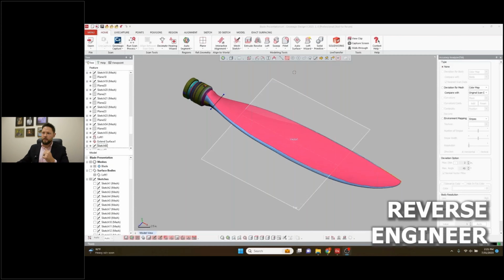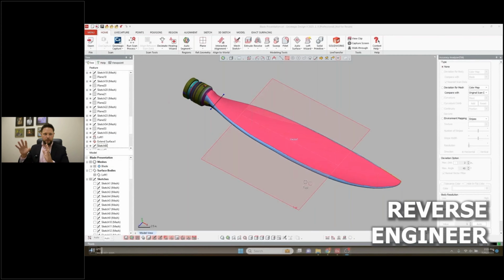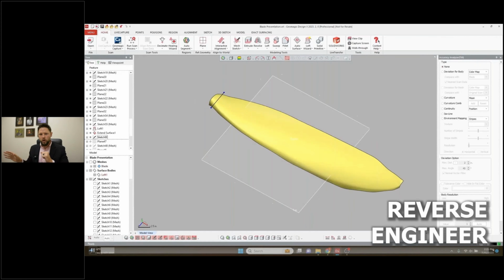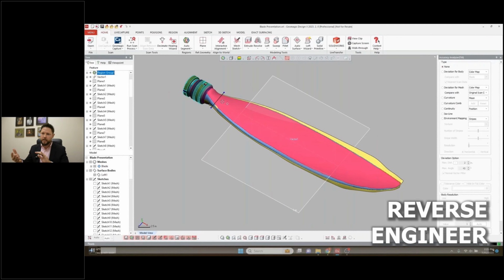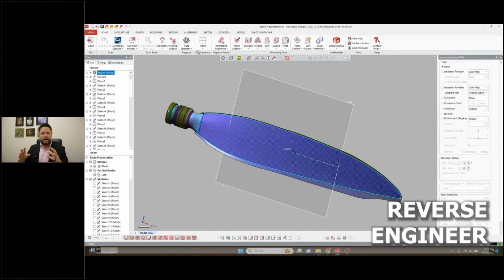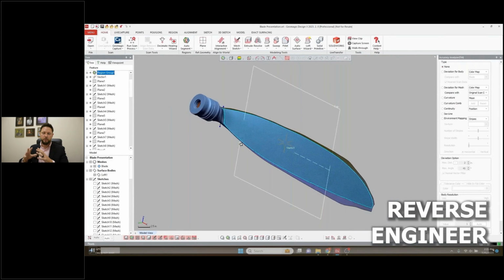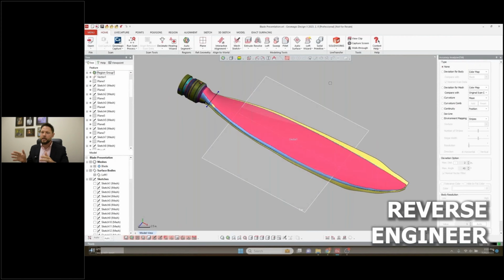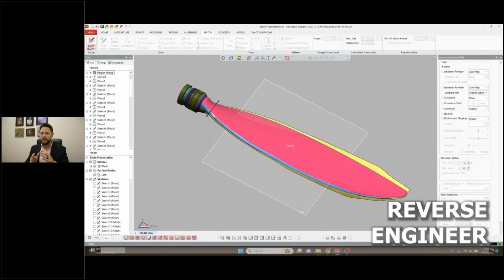So to start the video, again, this will be familiar to anybody working with any of the latest CAD programs. We've got the tools across the top. We've got our parametric tree on the left side there, so we can adjust things as needed, as you normally see. The way I've had this set up is I already have a few features extracted. So I've got one side of the blade done. I'll show you how we do that on the other side. What we're looking at here is the mesh already broken up into these auto segment regions. What the software does is it goes through and applies a region. They're not surfaces, but just areas on the mesh that it recognizes as individual features. And then we'll use those to extract the geometry.